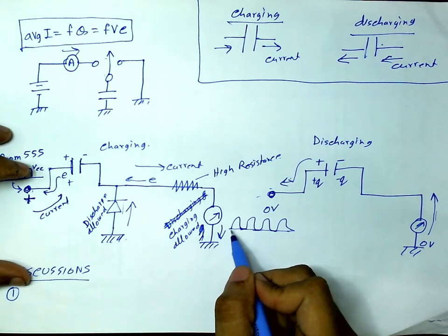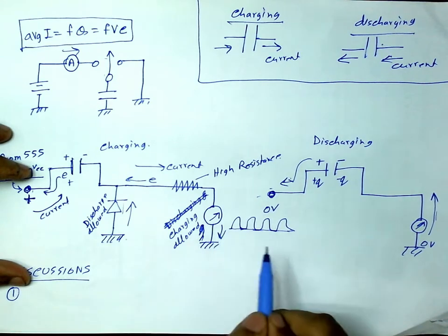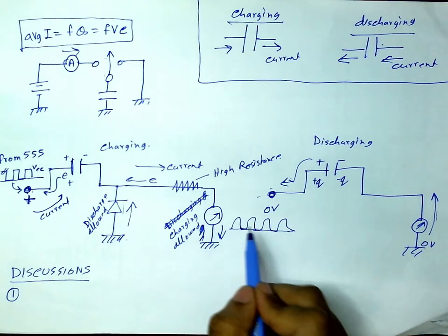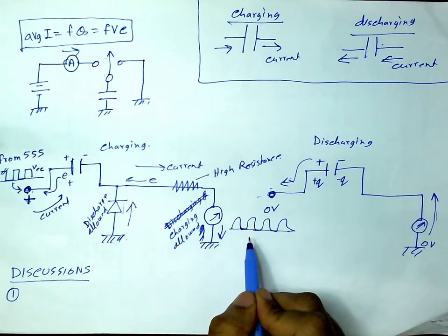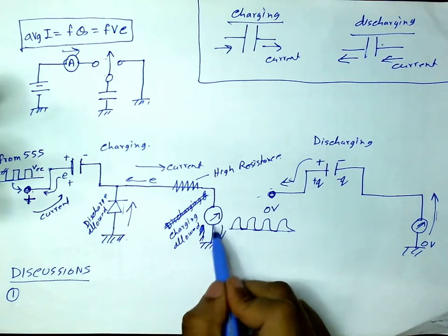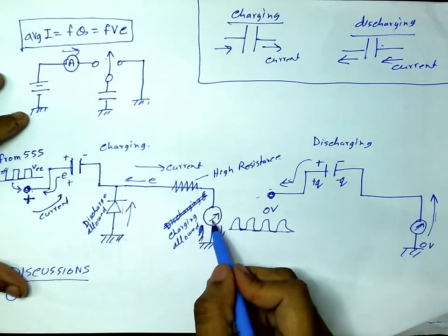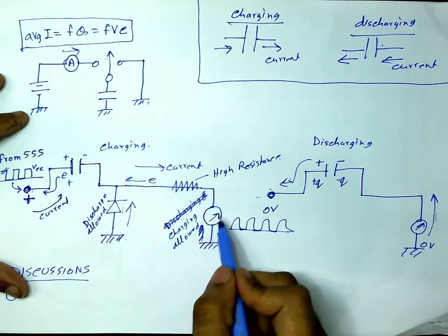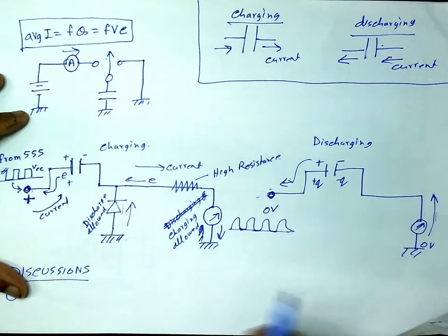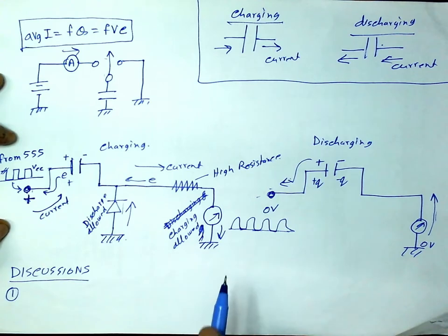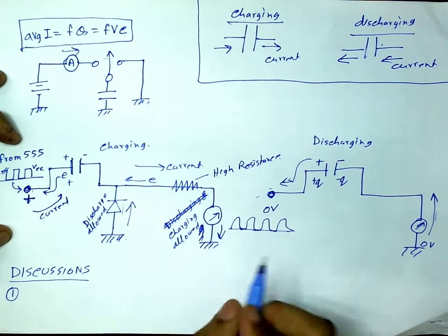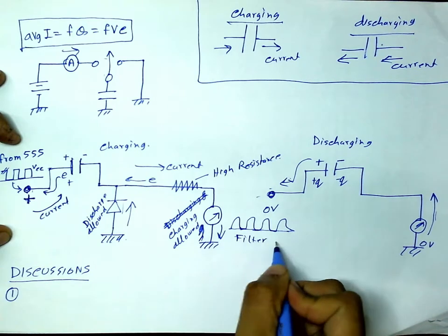But at least I'm sure that it's going to be oscillating through the meter, and this may even cause the pointer to oscillate if the frequency is not very high, depending on the dynamics of this pointer. This pointer may even oscillate. So we will use a small remedy, trick, a small filter. So we need a filter. A filter is needed.